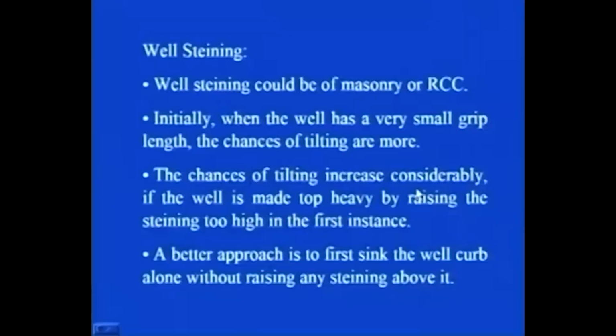So, first the pitching of the well curb takes place, and it is recommended that the well should be sunk only after you have cured the curb alone, and then only you should go for the raising of steining above that well curb. Now, after the pitching of the well curb is over, there comes well steining. So, let us see what are the various points that we need to keep in mind while going for construction and sinking of a well foundation.